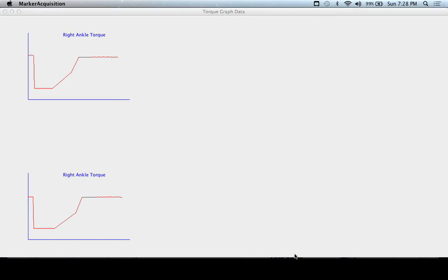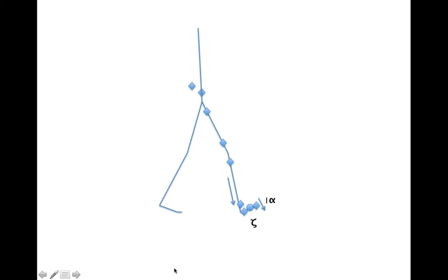After that, I will be working on recalculating the force, and this is actually a lot more difficult than calculating the torque. The torque was essentially a simple I alpha relationship. I estimated I using anthropometric data for the radius of gyration. It's given as a fraction of the segment length of, say, the foot or the shank or the thigh, and of course relative to the center mass or relative to the joint. So all in all, with a few basic assumptions that don't really take away from accuracy, the torque is pretty easy to generate. However, the force is a lot harder, and I think the reasons are fairly obvious.